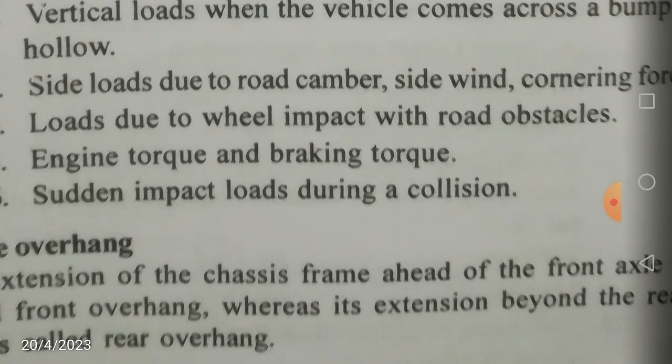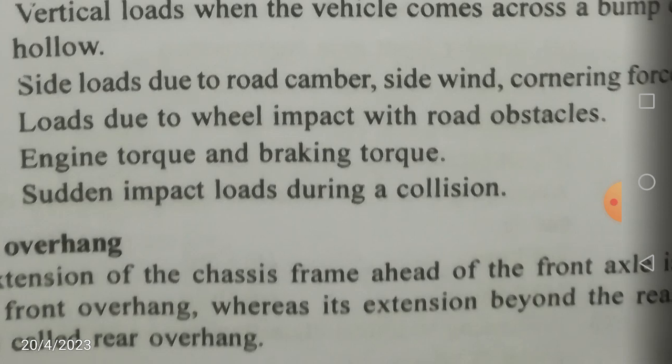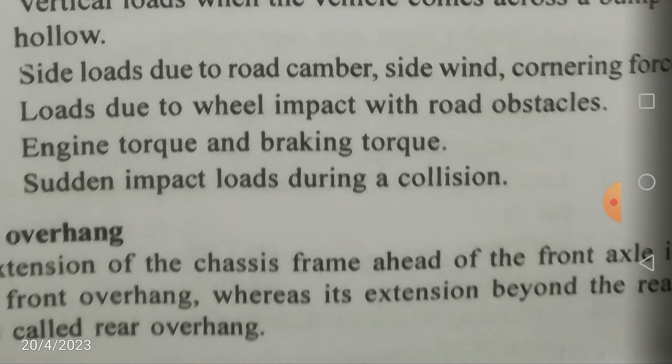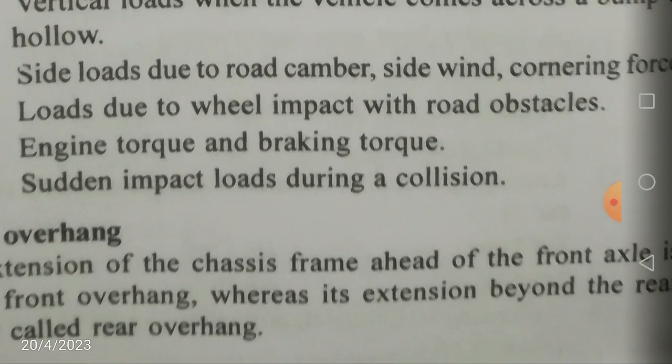So the power is coming from the engine through all this transmission system to the rear axle and hence the rear wheels, in the case of a rear axle drive. That's why your rear axle is also called the live axle. The front axle is called the dead axle, because your power comes from the engine to the rear axle directly through various transmission elements, like the clutch and mainly the gearbox. Transmission means manual transmission, means gearbox, friends.